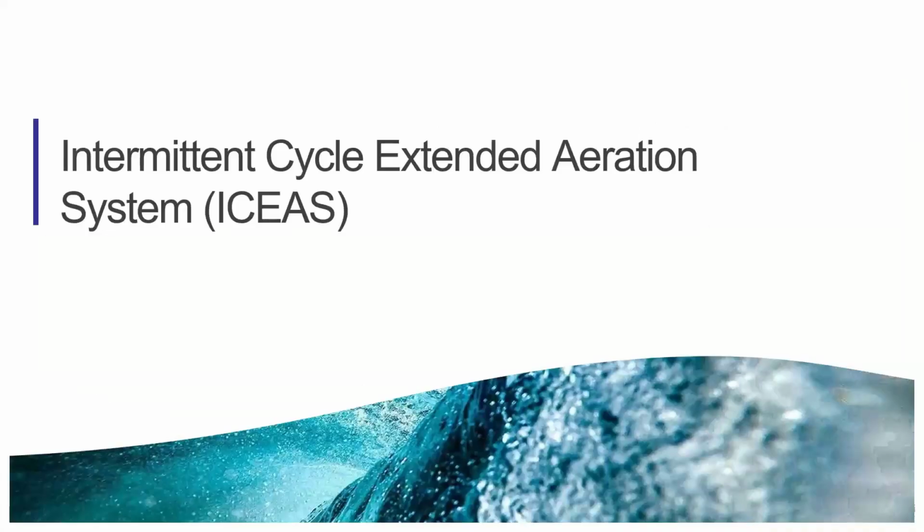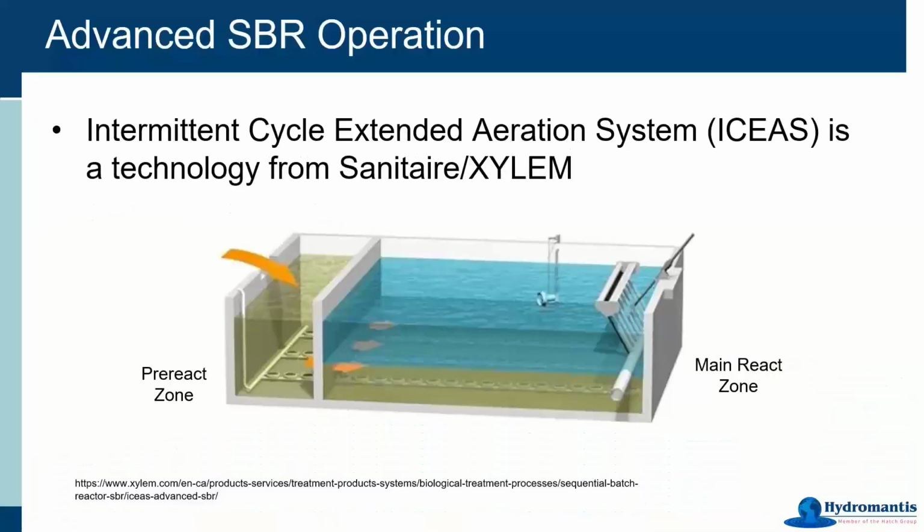Okay, so we'll start with ICS first. And this is a technology by Sanitaire. I borrowed a few pictures of it off the Xylem website. You can see here very clearly that this is an SBR operation, which has aeration in it and the ability to do decanting through this equipment over here. This level can be pumped up and down as needed.